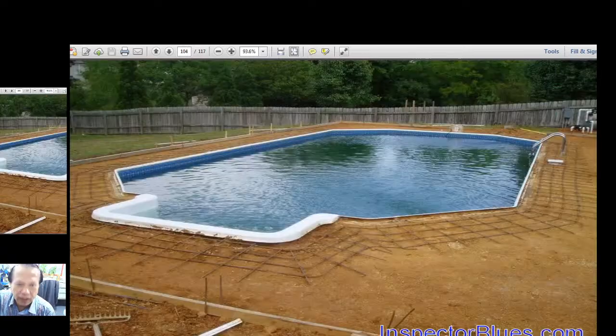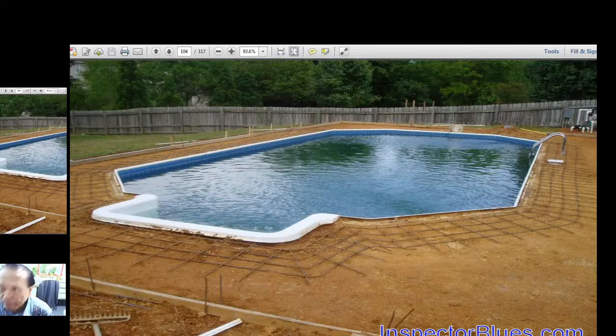So here, again, you have rebars around the pool. Your railing here, and the stainless railing on the right side, must be sitting on the rebars before pouring concrete. So be sure they are connected solidly before pouring the concrete.